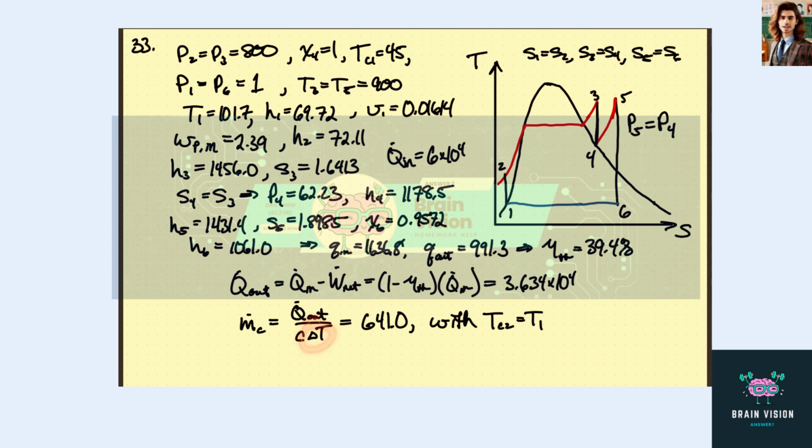And then we get the temperature difference. We have the temperature at the inlet, and for the minimum case, the outlet temperature would be the temperature here at 1, so that the outlet temperature of the river water and the process water have the same temperature. That would give us the minimum, which we would obviously probably need more than that.